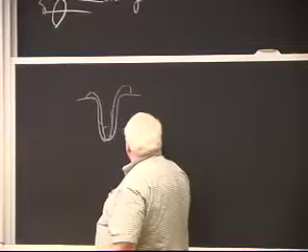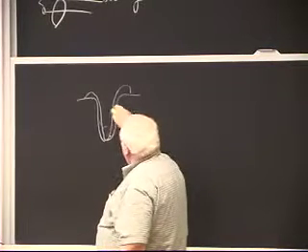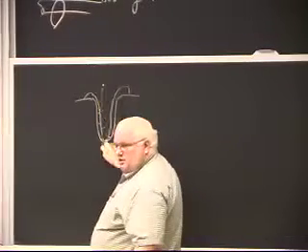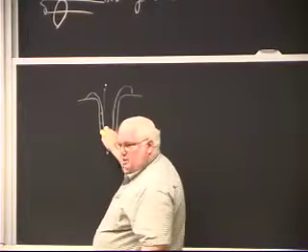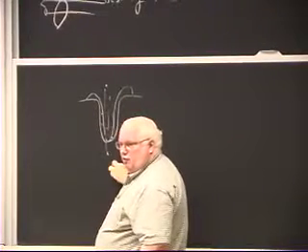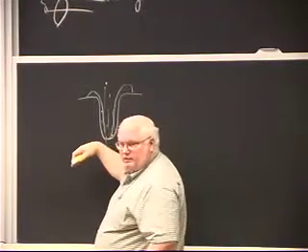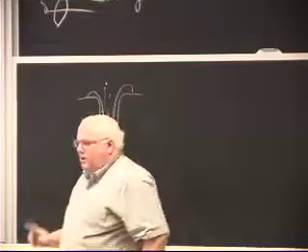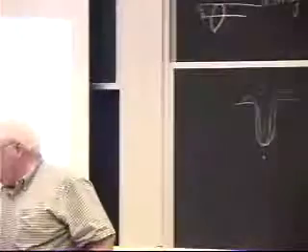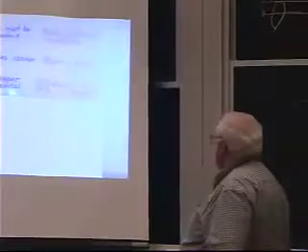If you do it in the horizontal position, then obviously everything slumps to one side and the thing keeps on shooting because the thing collapses on itself. You still have a hole all the way through if you rotated this 90 degrees. So you get deeper penetration because of that, about 30% in the horizontal position.